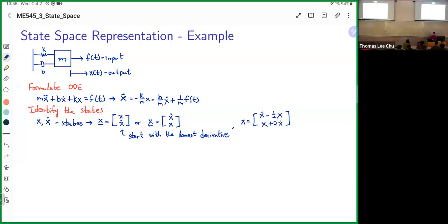Another question. I remember we knew the number of state variables because it was the highest order minus 1 times the degrees of freedom. So in this case, because it's x, the second order, there's 3, so minus 1, that's 2.